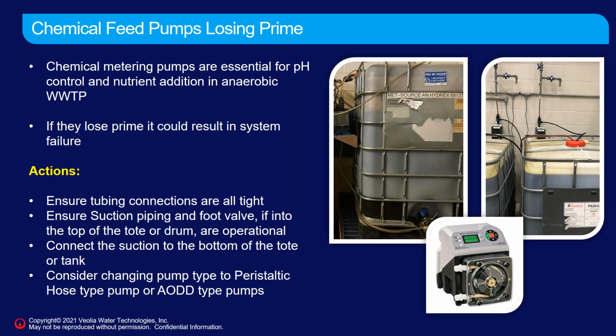And recently we've been changing a lot of our pump supplies to these peristaltic hose type pumps you see there, like Watson Marlow, Blue-White. These pumps are nice. They have a wide turndown ratio, plus they self-prime to very high lift heads. So there is some more maintenance with them because you've got to change that hose on some frequency, but they can help avoid a lot of the operational problems with those diaphragm solenoid driven pumps.